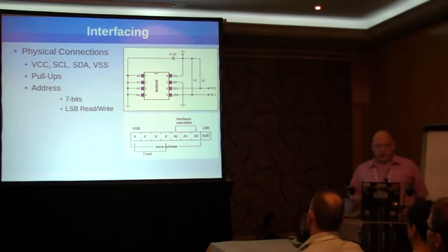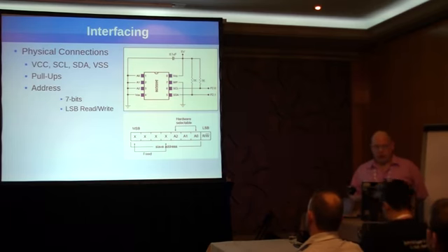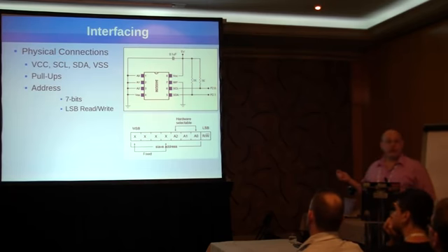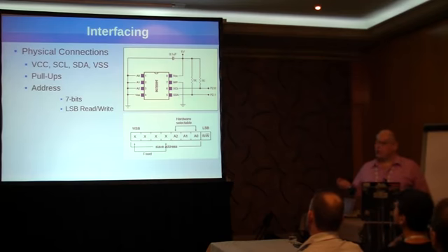In this example also, the EEPROM actually has 3 pins on the device itself marked A0, A1, and A2. These are bits that allow you to either pull them high or pull them low to actually change the address of the EEPROM. In our table, you can see that A0 corresponds to the first bit of the 7-bit address. So if you change that as a pull-up resistor, that would become a 1 in that place. This allows you to take one EEPROM type and have multiple addresses available to you.